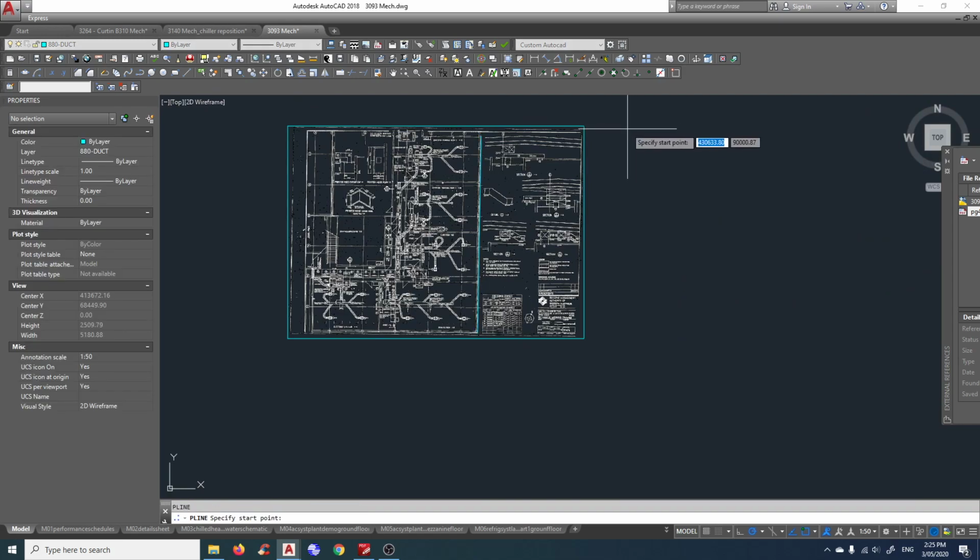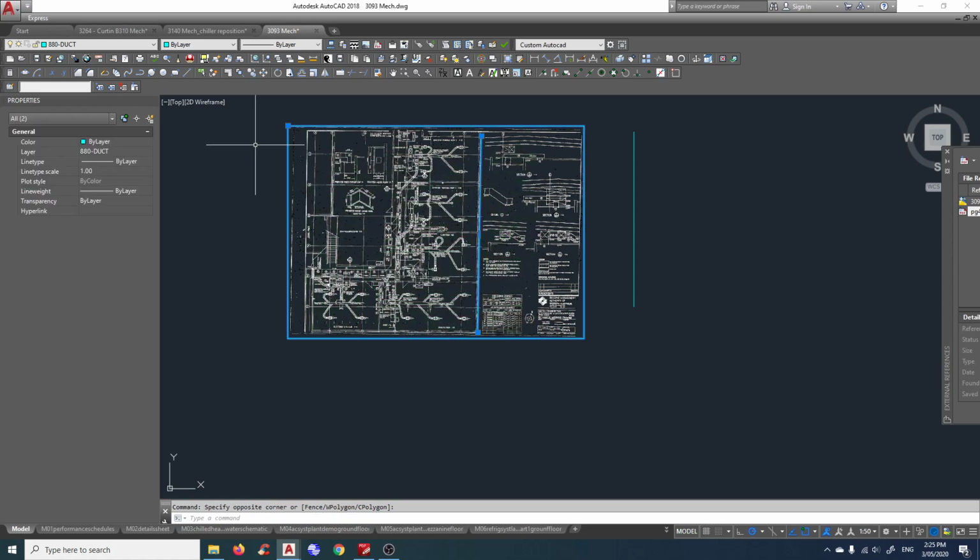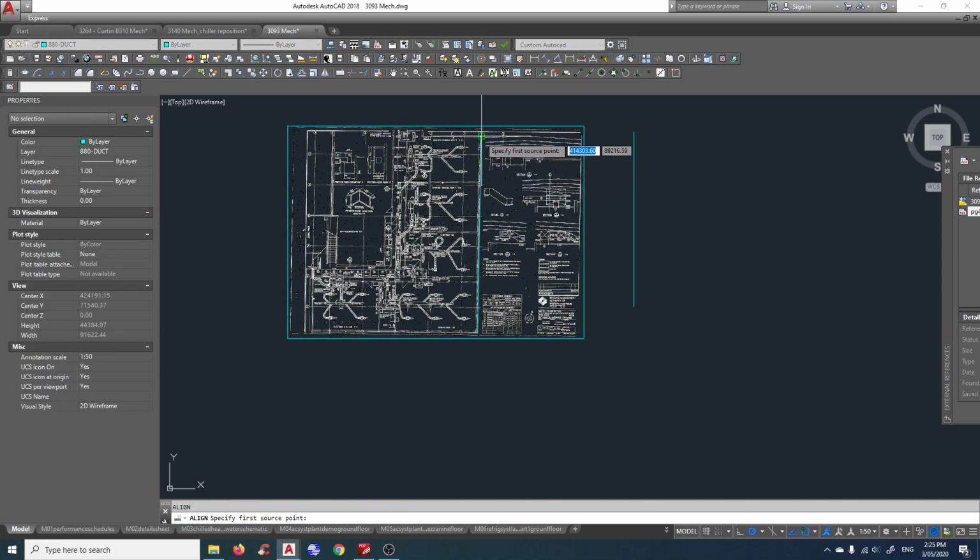And then we're also going to draw a straight line. Select this drawing, type align, A-L, align, top point goes to top point, bottom goes to the bottom, and read the command. Would you like to specify a third point or continue? We're going to continue, so press enter.